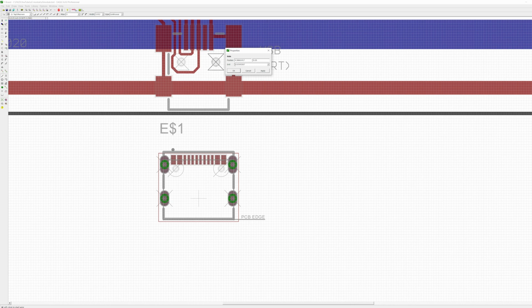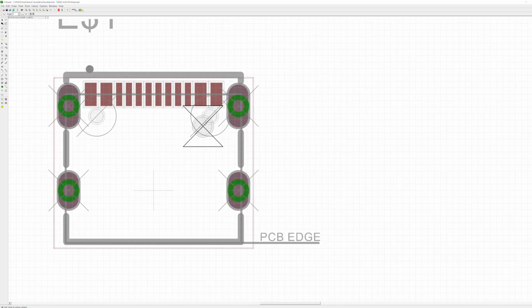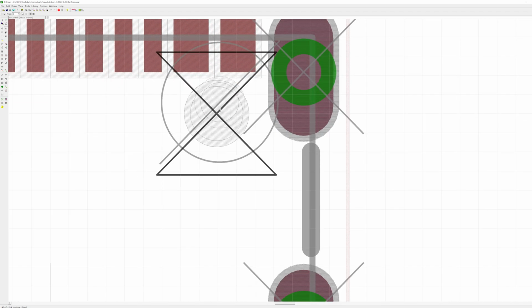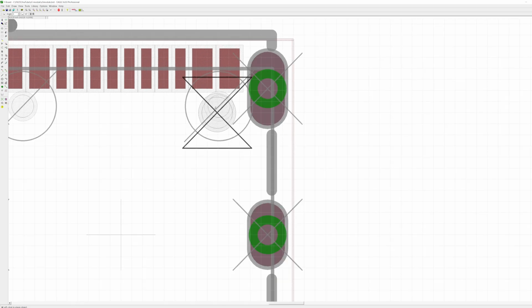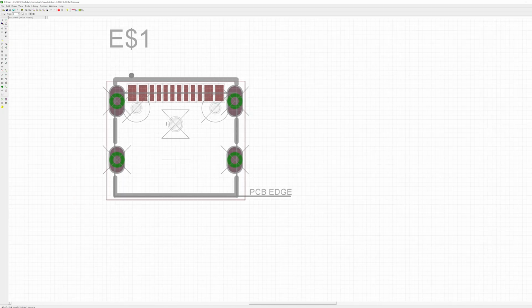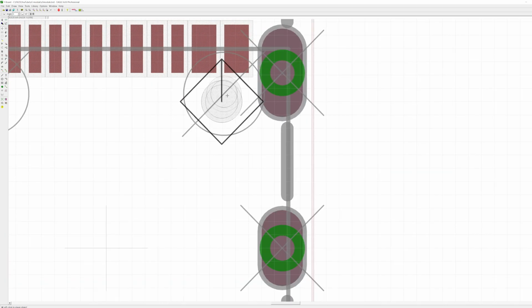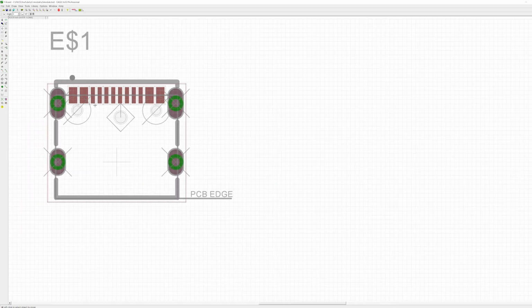I'm going to look at the properties here. Okay, so that's 0.035 drill size. Okay, I guess I'll just copy that for now, and we'll get it close. I think I'm going to have to make my grid twice as fine to get these drills placed properly. But I'm noticing that that's a pretty large drill size. So I'm just going to shrink it by 1, and let's see if that's close. Yeah, it's still bigger, but it's close.